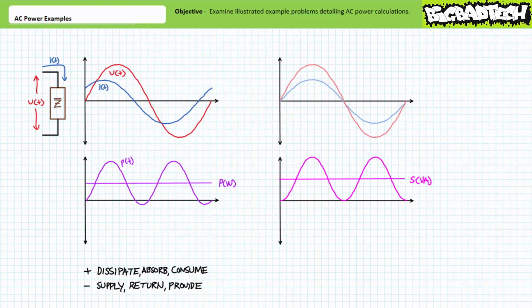If apparent power is to be likened to an ideal scenario in which voltage and current are perfectly in phase with one another, and all power is positive, it's almost like real power is what's left over after phase shift effects are accounted for. In keeping with this observation, one can think of a third type of power known as reactive power, symbolized as a capital Q and measured in units of volt amperes reactive, or VARs, where reactive power is that power not dissipated, but rather cyclically exchanged with the power supply.